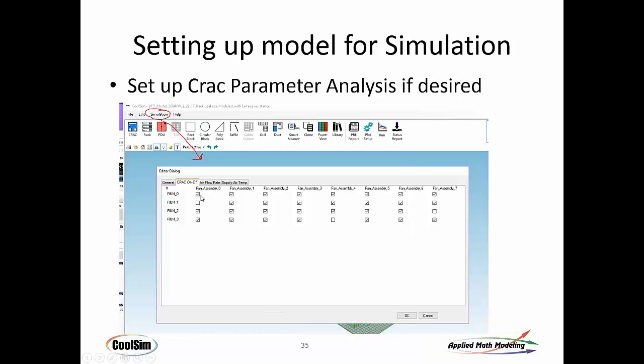So you can see in this example, we have 7 cooling units. This particular one, I called them fan assemblies because we're modeling a free air system or an air side economizer system. But you see here in run 1, so run 0, they're all on, and run 1, I've got one shut off and so forth. So I'm beginning to study the effect of maintenance modes or down modes on the various fan assemblies.